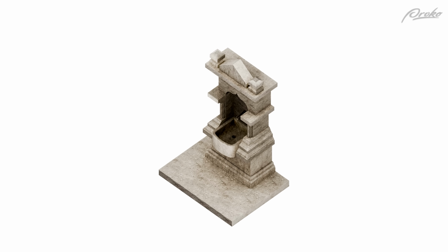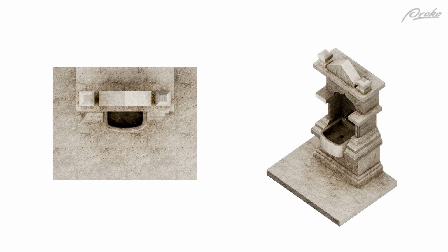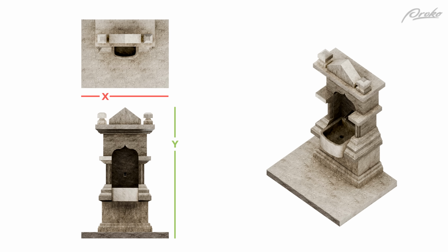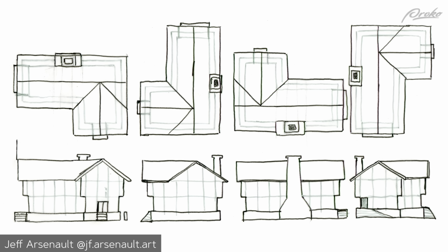You may want to do a little pre-planning for how it will best fit on the page, keeping in mind our principle that if a top view swivels 90 degrees to show its front, it will all line up. The widths won't change. And if the front view swivels 90 degrees to the side, the height lines will stay the same. Now we have orthos.